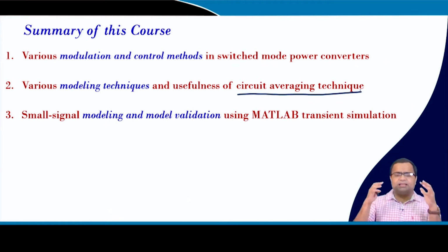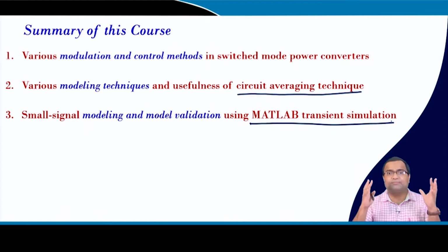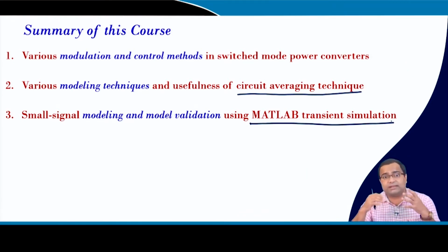Then we introduced small signal modeling as well as derived small signal transfer functions. We validated those transfer functions using MATLAB transient simulation, and this is one of the very important features, because you want to understand whatever you have designed by means of transfer function and compensator, whether those models are really valid, whether your design using the linear model by closed loop simulation is going to match with the actual switch simulation.